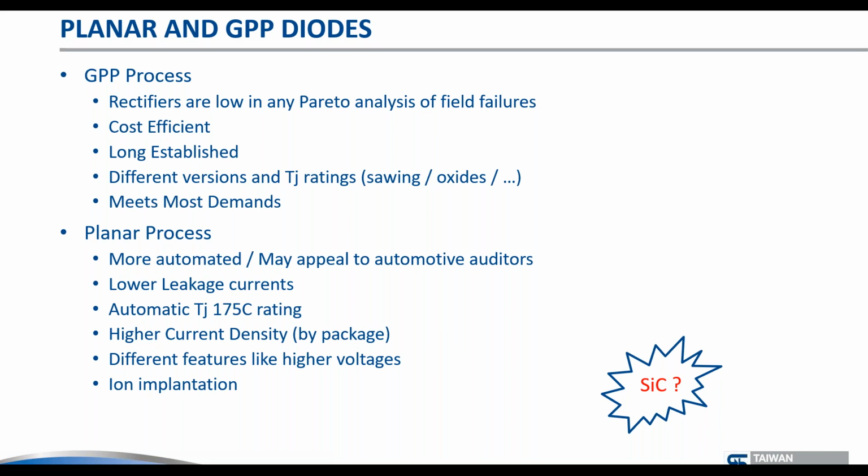It has a positive temperature coefficient, which doesn't help rectification issues, and its main issue is that it has very small die sizes, which means that if there is a surge, combined with this positive temperature coefficient, it is not terribly stable. It doesn't have very good surge capability, and in a lot of applications there are surges. So we don't see this massive replacement of silicon by silicon carbide.